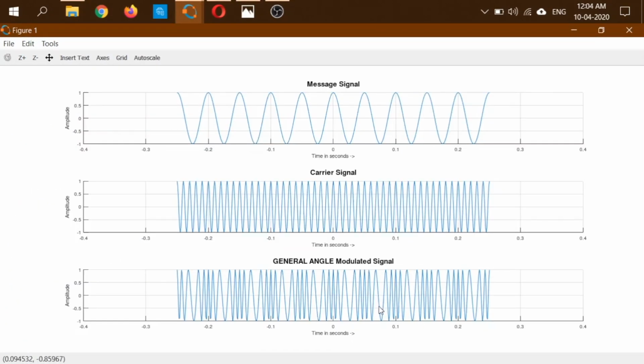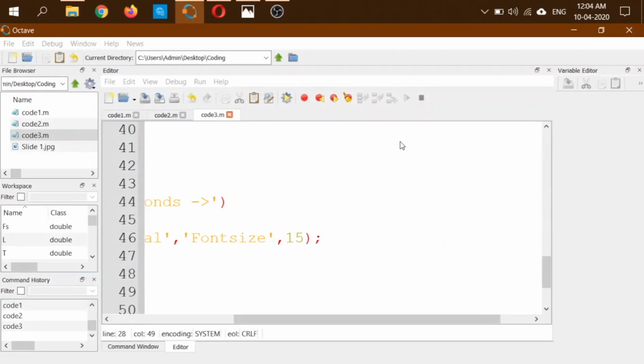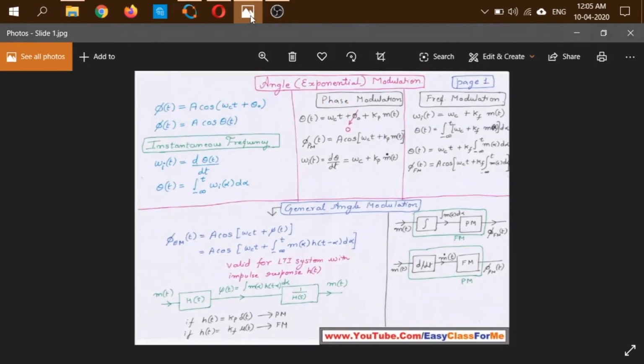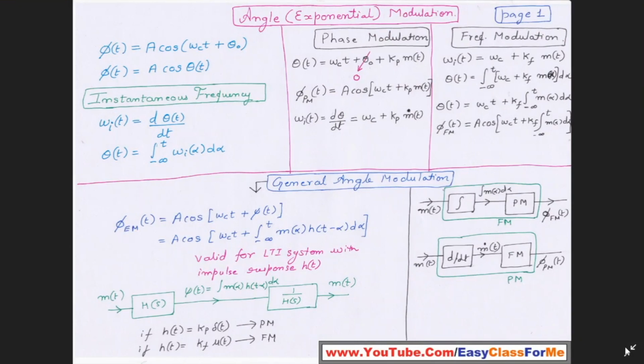Again, the results look no different from what we have done earlier. This is how you can see the waveforms in the time domain. Side by side, I should also have plotted the frequency domain representations of these, but it's not very easy here, because as we said earlier, this modulation is in general not a linear modulation, it is an exponential modulation. So Fourier analysis cannot be directly applied here. We will talk about that more when we make calculations on bandwidth, etc., for FM and its various variants. So we will see it there.